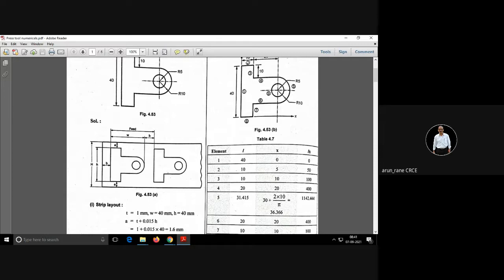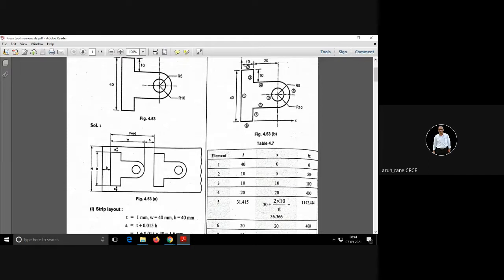अभी इसका center of gravity कहाँ पे रहेगा? इसका half. Okay, so ये 10 है. This is 10. So 10 का half, that is 5. So 5 from this in horizontal direction. So length is 10 and x is the distance of center of gravity of this from this origin. So that is 5 and L into x is 50. Is this clear? This row is clear? Yes, sir.